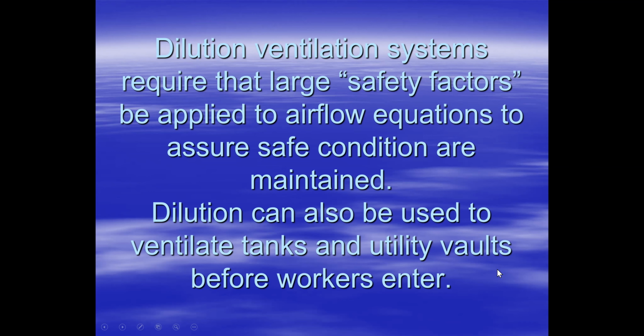I can use the dilution ventilation approach also for spaces that I traditionally consider confined spaces or enclosed spaces, as long as I ensure that, one, when I start diluting that air, I do not take something that's over the upper explosive limit, which at that point doesn't present a fire and explosion hazard because it's too rich to ignite. And as I dilute that down, I'm careful with how I handle that exhaust and that air in that space as it passes through the region in which it can ignite and explode.